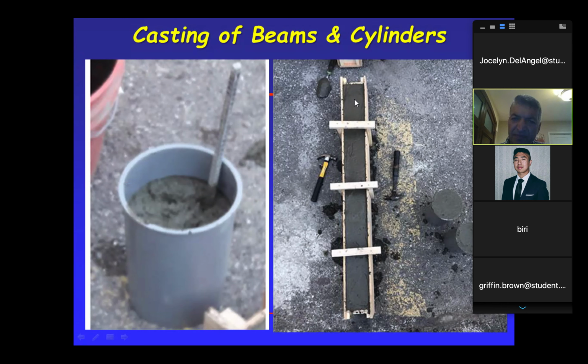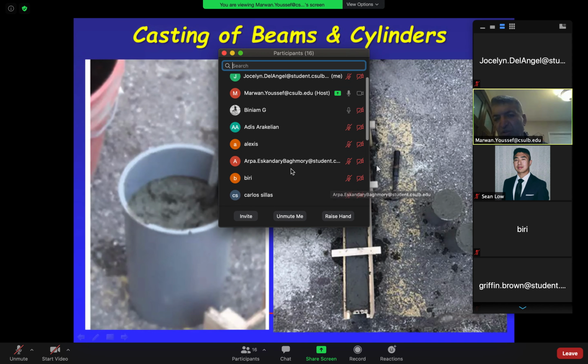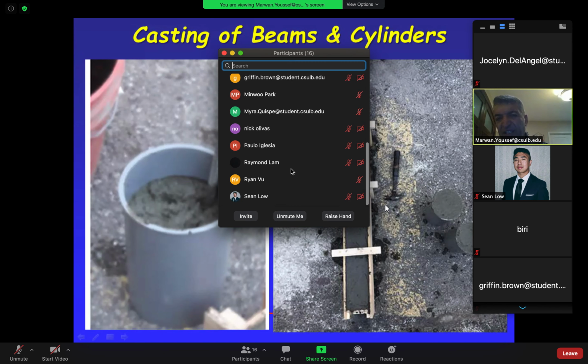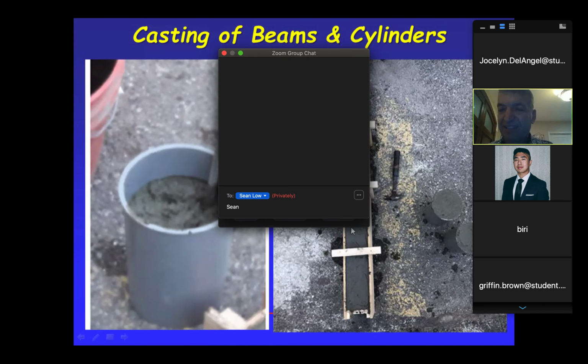And there's the beam. There's the spatula we use to take the concrete from the bucket to here and there. And then those 2 hammers, the students used to tap on the sides carefully, as if you're vibrating the mix, so it can seep down, so no voids in there.